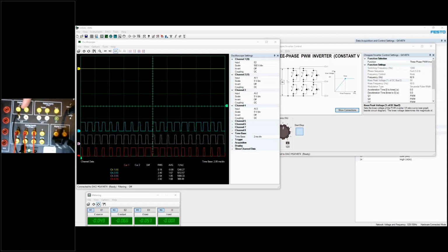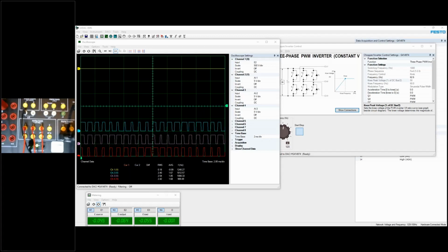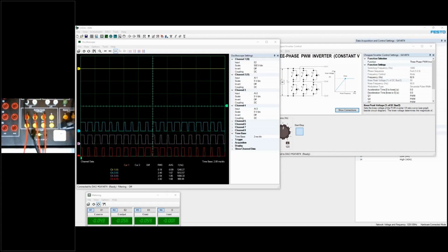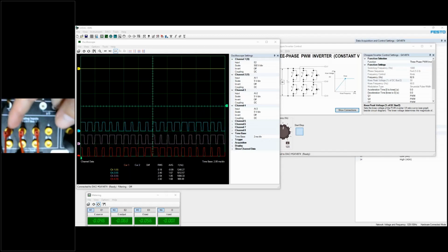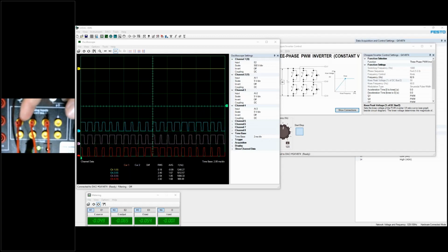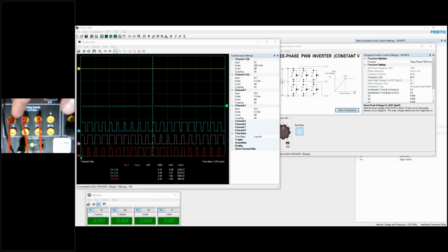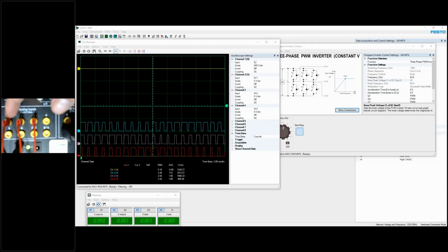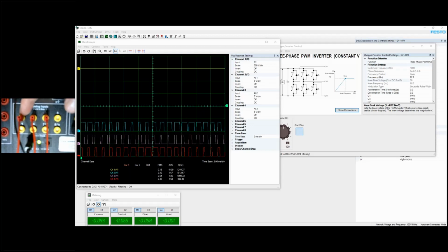And then you can take these outputs to feed any circuit you might want, or in this case, I was using analog output 1 to feed analog input 1 here. This input here, analog input 1, is the one for which I said in the software that the control signal for the duty cycle would come in.